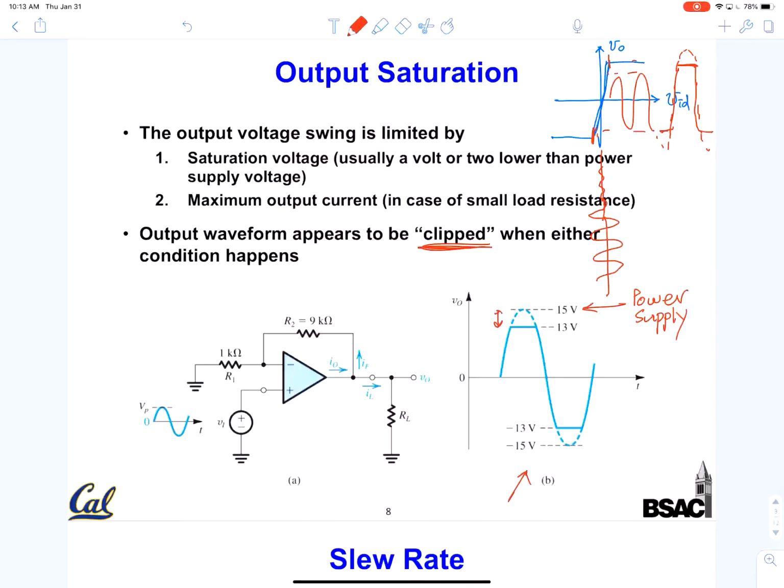But this clipping creates a distortion. If you have a sinusoidal wave at audio frequency, you hear a monotone sound. Our ears are not very good, so we typically use instruments called spectrum analyzers. You will see a single frequency at that particular tone. When you start to introduce clipping, you start to generate harmonic frequencies, new frequencies that are not in the input.